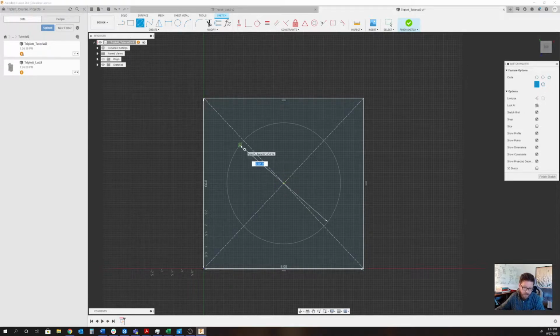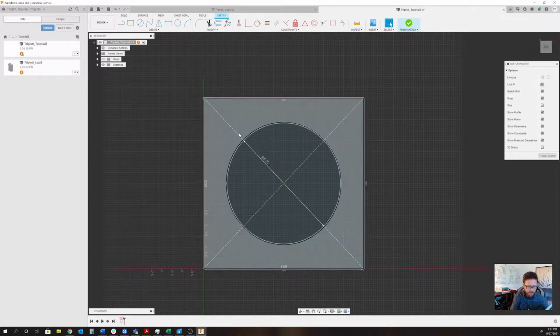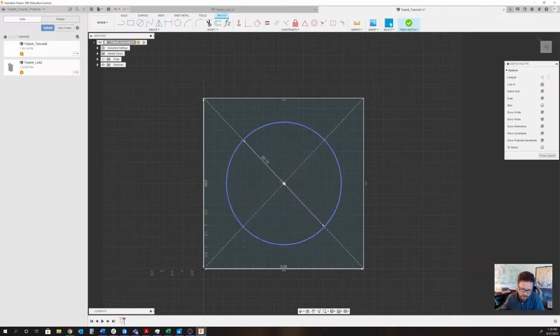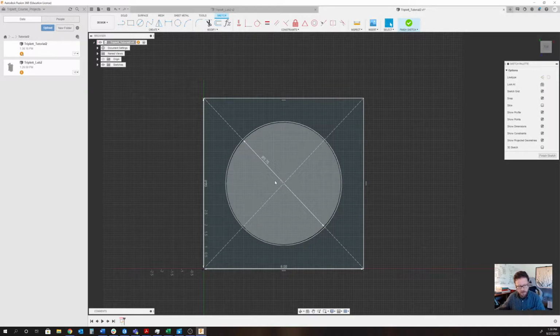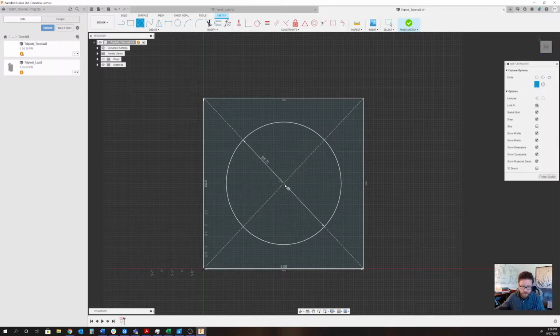The next thing I want to do is create the inside shaft of the spiral staircase. Because I've done these two crosses, I can find the dead center there. I'm going to go from here out with the center diameter circle, and I'm going to make it a diameter of 5.75, I think. Let me double check my notes quickly. Yes, it should be 5.75. Make sure you're following along. We've got our interior space, and now we want to create another circle on the inside that's just going to be a perfect column, and that one will be smaller. That's only going to be 1 meter in diameter. Okay.